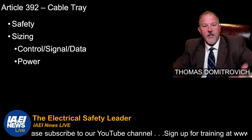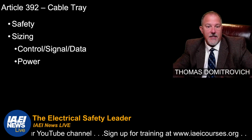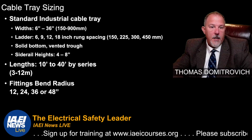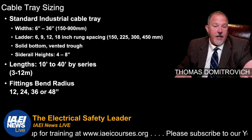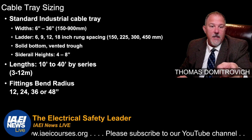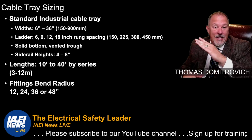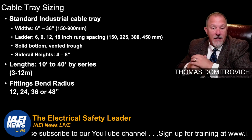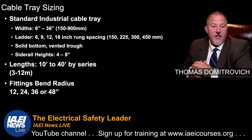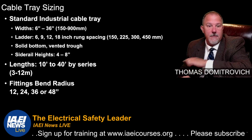Safety, sizing, control. Article 392 gives us all the safety and the sizing for the control signal data and the power cables. 6 to 36 inches, your standard. Your ladder is 6, 9, 12, 18 rung spaces. Solid bottom vented trough. Side rail heights 4 to 8 inches. Lengths 10 to 40 foot. Fittings, bend radius 12, 24, 36, or 48 inch bending radiuses.